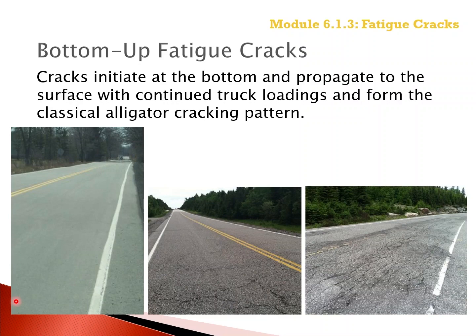Bottom-up fatigue cracks initiate at the bottom, and propagate to the surface. They initially appear as short longitudinal cracks, but with continued truck traffic, form the classical alligator cracking. So this photograph shows the short longitudinal cracks in or adjacent to the wheel path.